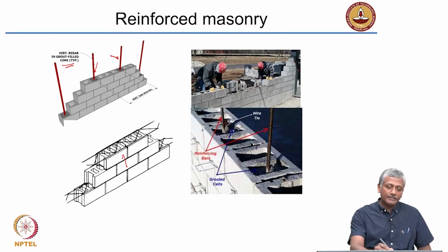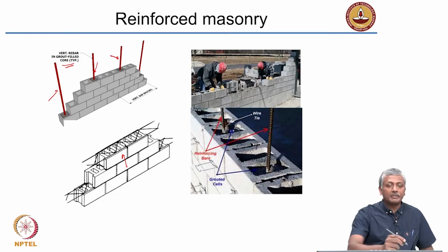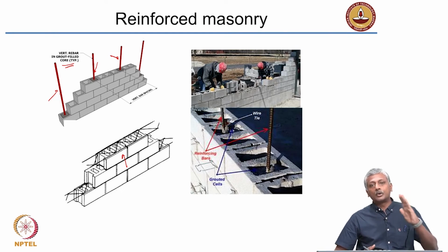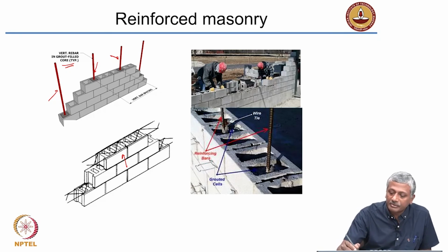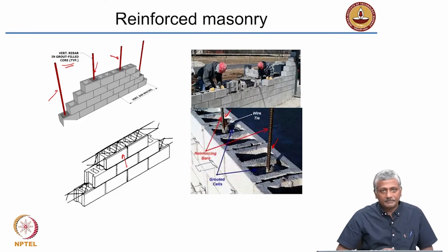Again, you see here, reinforced concrete block masonry can also get horizontal steel to reinforce it, but mostly we are talking about these vertical steel members that impart the lateral load resistance for the wall. Again, just to give you an example of real construction, you see these blocks where the steel has been inserted not in every cavity, but in every third cavity.